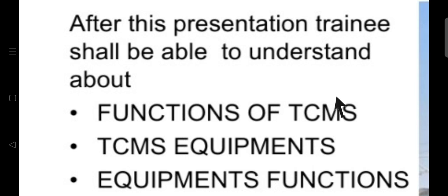In the TCMS page, the train driver needs to go to the camera page. There would be some sound, or some indication, that appears on TCMS, and through that indication the driver would get to know the camera of that particular car is not working properly. So from this example, one thing that is clear is that TCMS is also monitoring the things happening in the train.